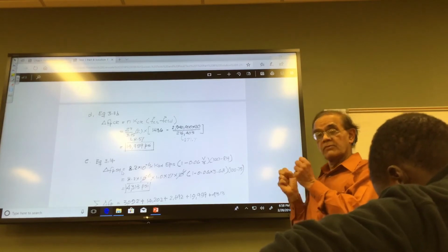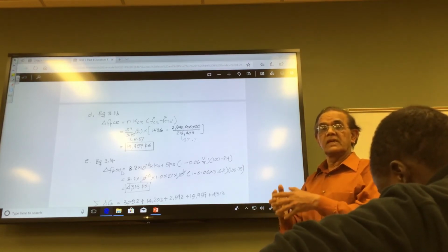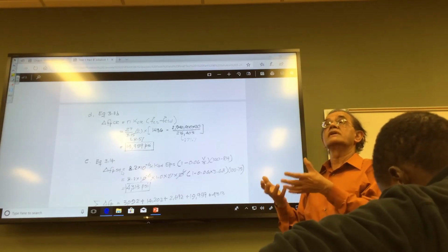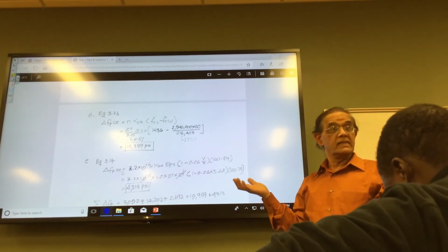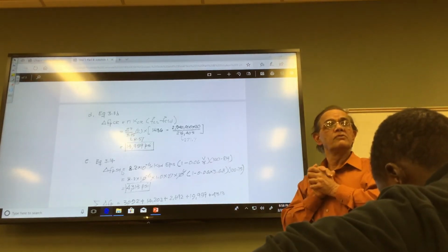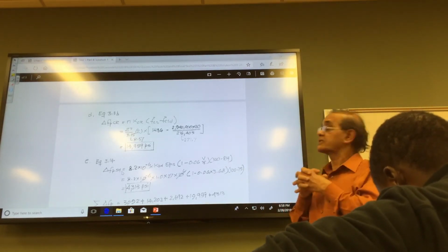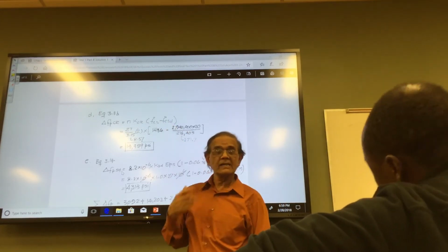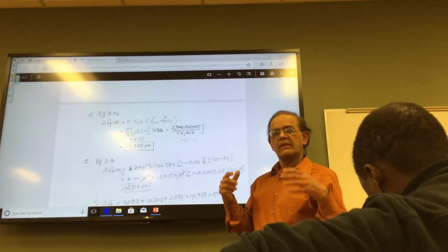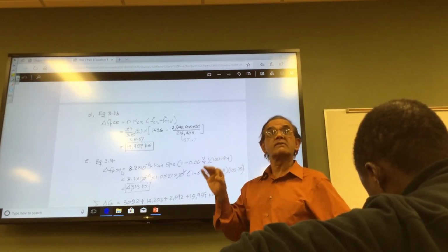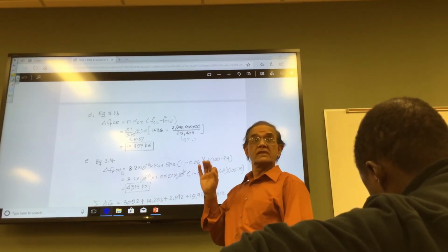when your creep for the most of the time happens under the influence of superimposed dead load that is already there, because we are considering years, 5 years, right? So superimposed load is already there within a matter of few weeks, compared to 5 years. So you use this stress, and this stress is actually helping you, because we are calculating the stress in concrete at the center of gravity of the pre-stressed tendon, right?